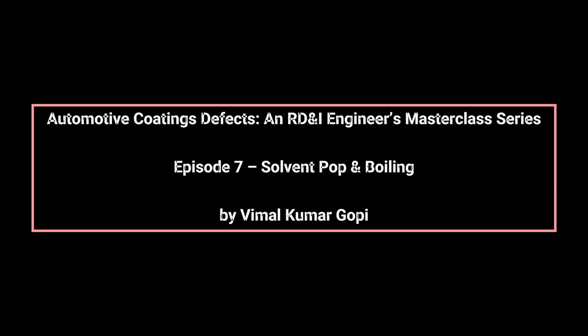As film thickness increases, the time required for tail solvents to migrate to the surface rises non-linearly. This is why solvent pop often appears only when DFT crosses a critical threshold, even if the same formulation sprays cleanly at lower builds. In OEM plants, this frequently occurs on horizontal surfaces, overlap zones, or repair areas where local film build unintentionally increases. Flash-off time is equally critical.